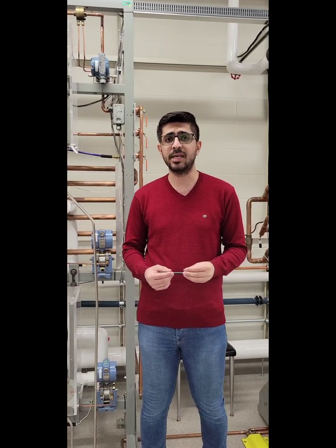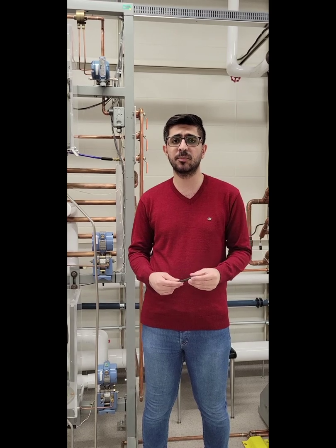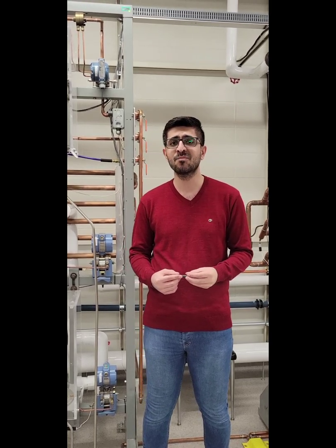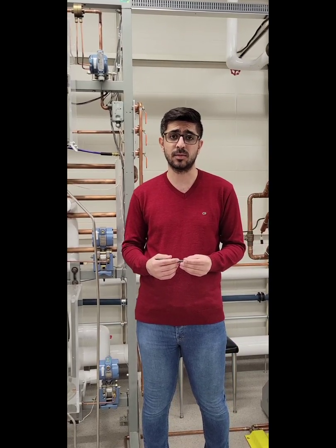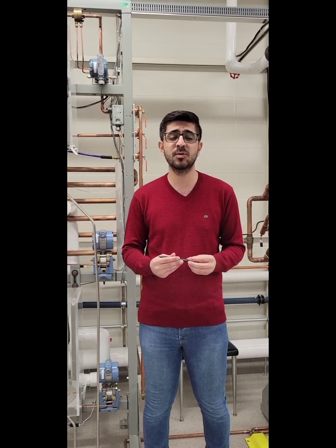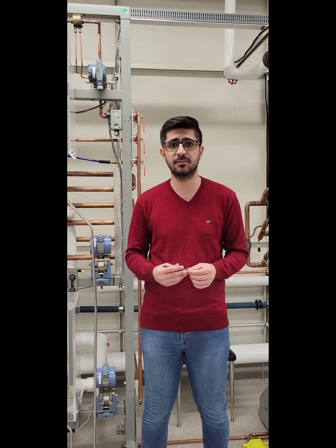Hello everyone. Today we are going to do the third lab of CHE 446. The objective of this lab is to identify a first order plus dead time black box model using the collected data for the relationship between the acidic flow rate and the temperature of a single tank system using the step-test response. So in this lab, we will address the estimation of process transfer function under the different operating conditions.